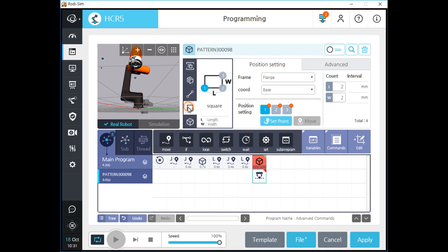In this box type pattern, you need to make 4 waypoints and 4 interval counts to complete this command setting. Let's save 4 waypoints step by step and make your own box pattern like me.